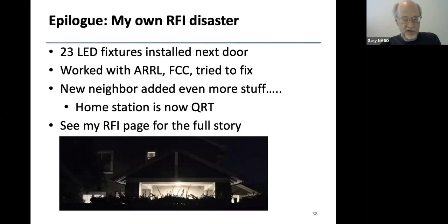So the epilogue here, and there's a nice report on this. Some people saw my talk at Pacificon. I gave this talk. My neighbor installed a bunch of LED light fixtures, and I went all the way up to the FCC. I always wanted to do that. I don't know why. I'm a glutton for punishment. And we actually did make an attempt at fixing it, but the fixtures are very difficult to mitigate, and it was a 20 dB solution to a 40 dB problem. Then a new neighbor moved in, and they installed, well, guess what? SolarEdge with panel optimizers. So it got even more noisy.